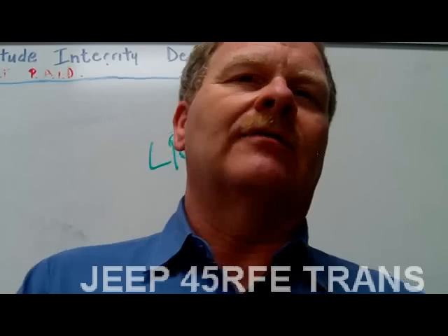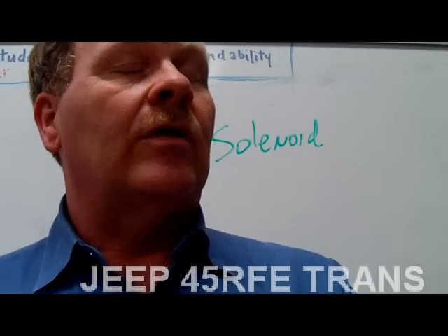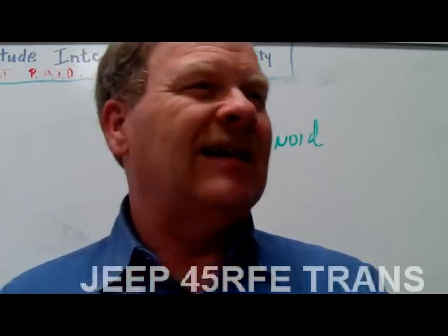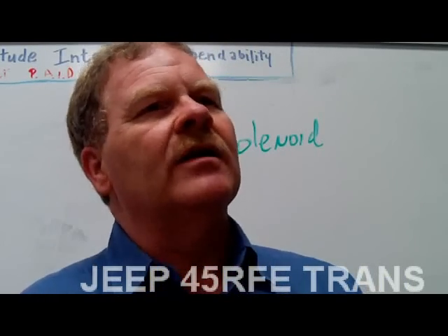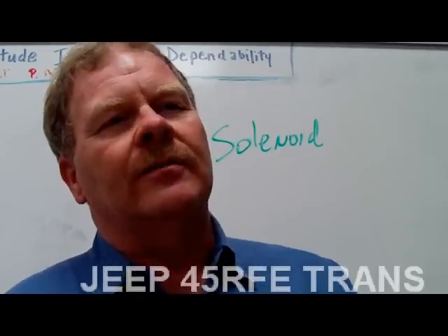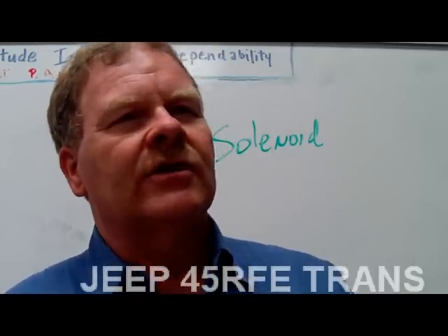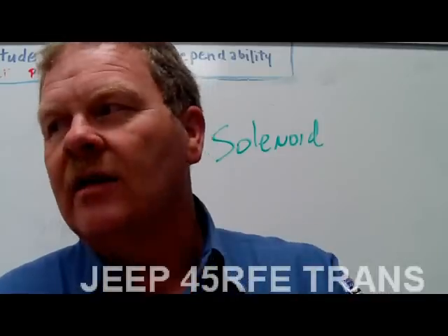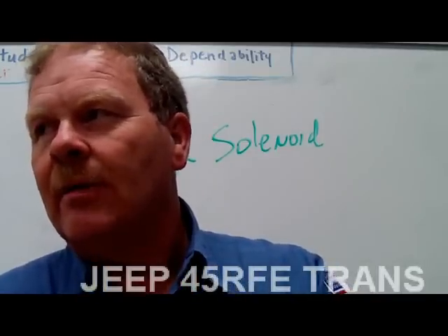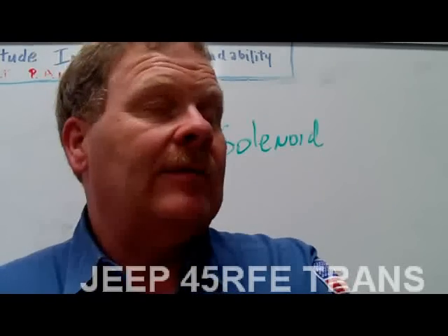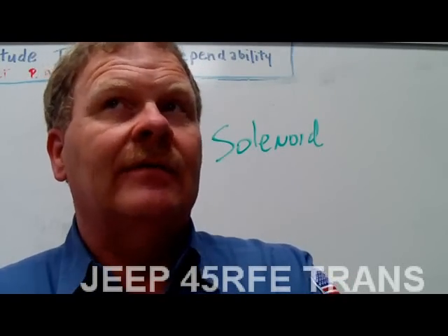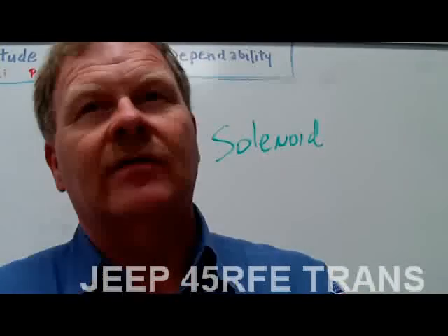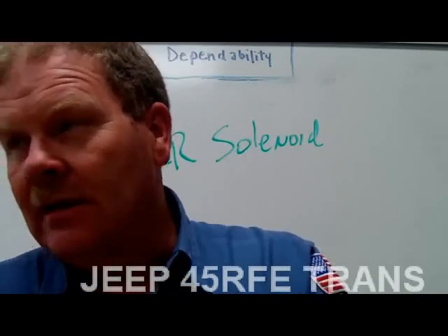I'm not going to pay top dollar for something, even though on her car it probably just needs a transmission pressure control, the transducer. You can find one of those. It's not that hard to put in there. And we used to have to replace those all the time when I was working at a Jeep dealer. So if you know the vehicle well enough that you feel sure you can pop that on there and it'll take care of it, it may be worth that. But she needs to be aware that you're not going to be able to squeeze $3,500 out of it if sometimes the transmission doesn't work right. And it's got other problems.